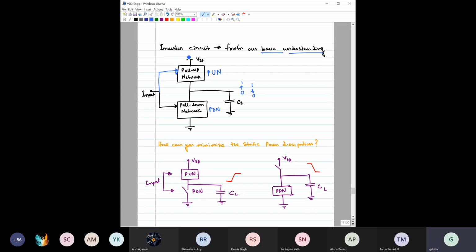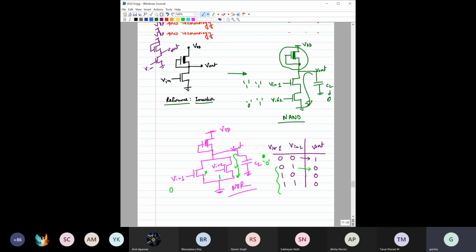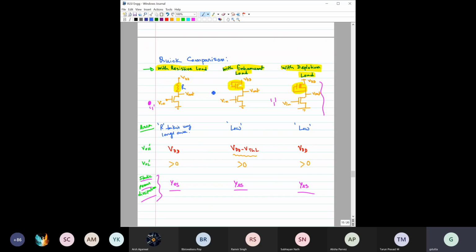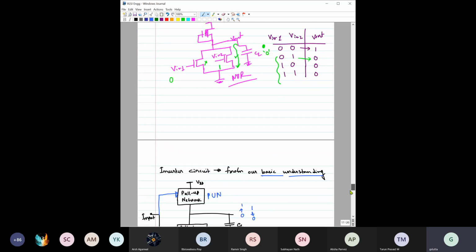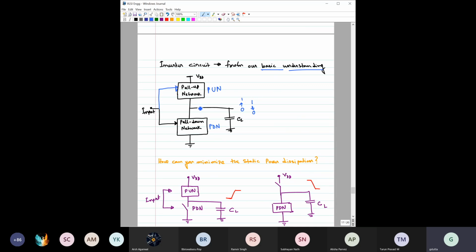No harm in this, right? We can connect this input to both the pull up network and the pull down network. So far we do not need to, because if you see the earlier techniques, here is the resistor, so no need of any input. Here the gate input is already connected, shorted with here. Here this input is already connected with here. So we do not have any requirement of connecting this input to the top load or the pull up network. But if there is any requirement from any design point of view, then we are free to do that.